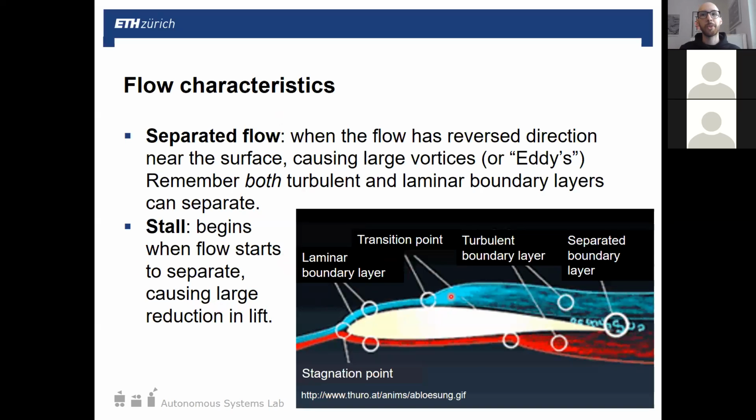Coming back to turbulent flow being attached and still generating lift, I can give an example: even commercial jetliners have specific little bumps along the wing that are actively trying to generate turbulence. They actually want the turbulence over the wing. The reason is that turbulent flow is a bit more energized and can stay attached longer at higher angles of attack. This can delay separated flow, basically. You're trying to stay attached longer, so you can go to a higher angle of attack before you reach the unsafe stall condition.